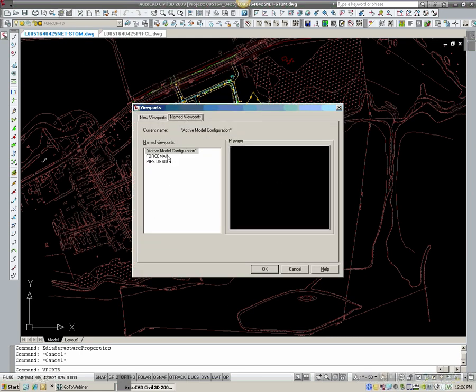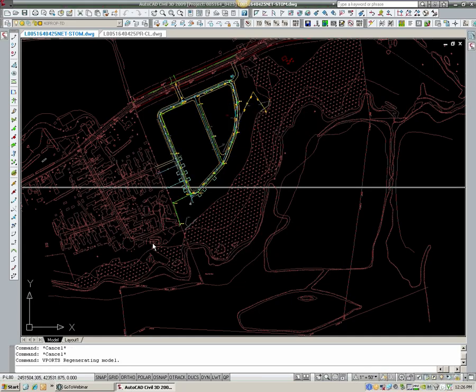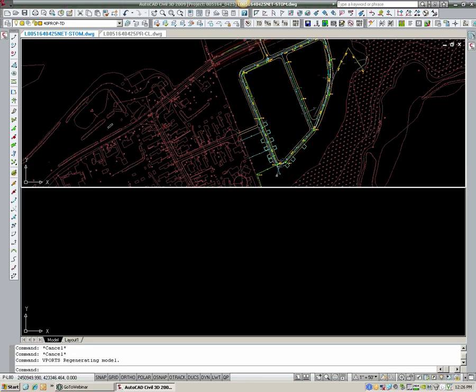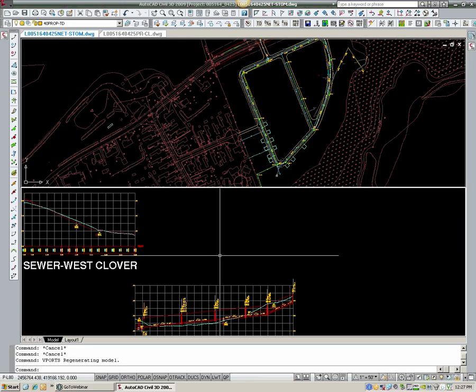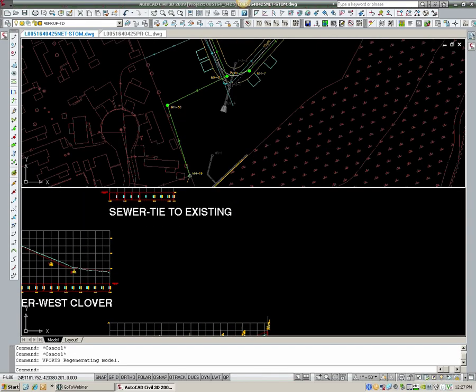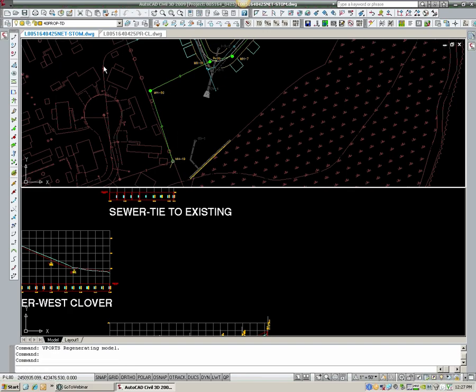And we're going to go and place this on some profiles. Let me split my view here into 2 different screens. And a tool that I want to feature or highlight here is that you can create an alignment in Civil 3D right from the network parts. So just like in Land, you still have an alignment and then your parts are drawn on top of that. I think in Land we thought that pipes were connected to alignments, sort of the same thing, but really they were 2 different objects, and the same thing here.